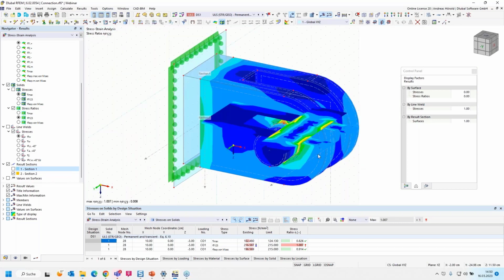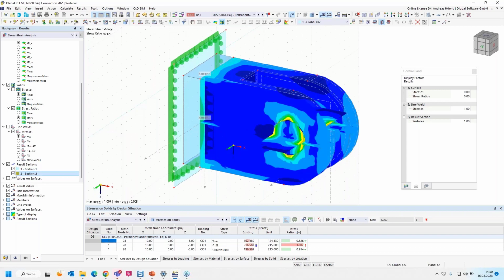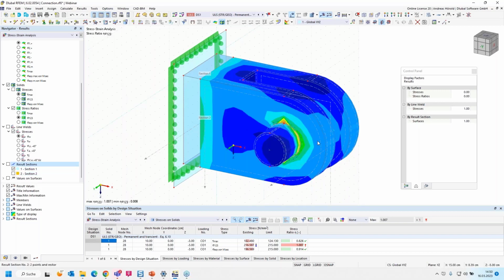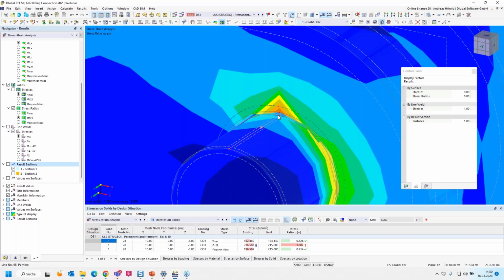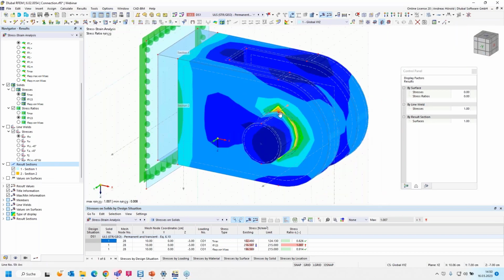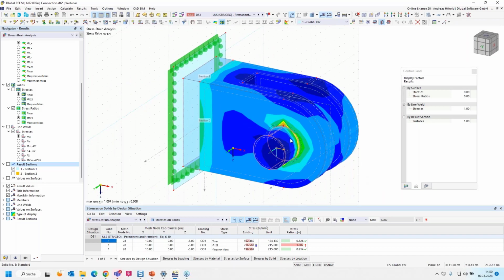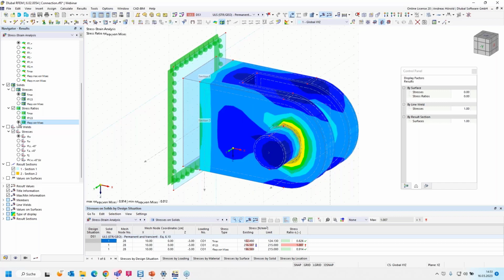Yeah, and then you can print such sections in the printout report. And in that case, here seems to be the maximum value. I print only this view here in the printout report, but for example, for the principal stress, tau stress, and the equivalent stress. How to do that? Here left at the top, print graphics to printout report.